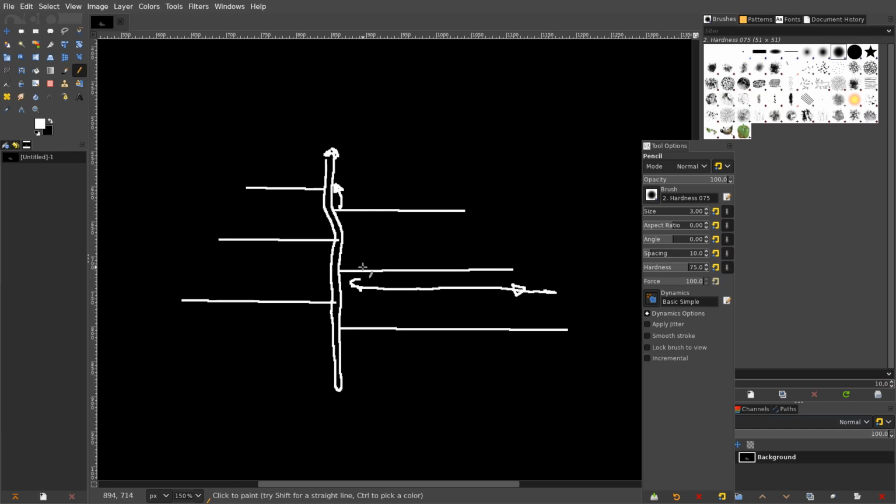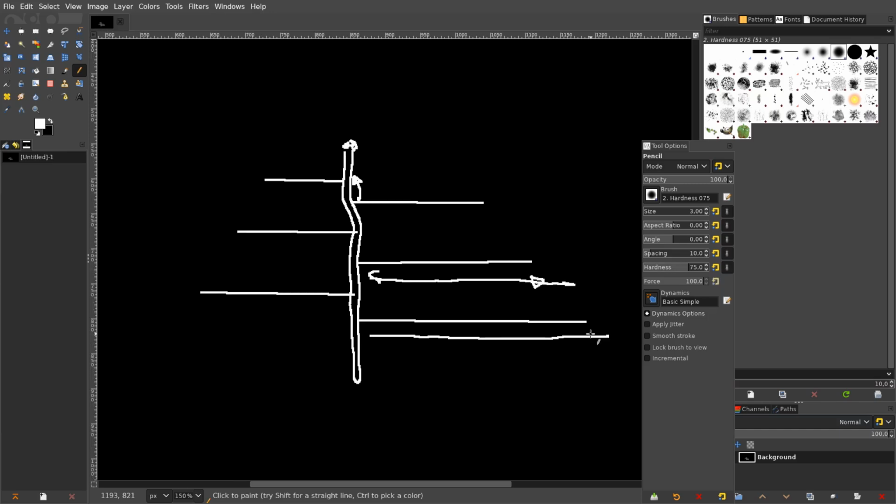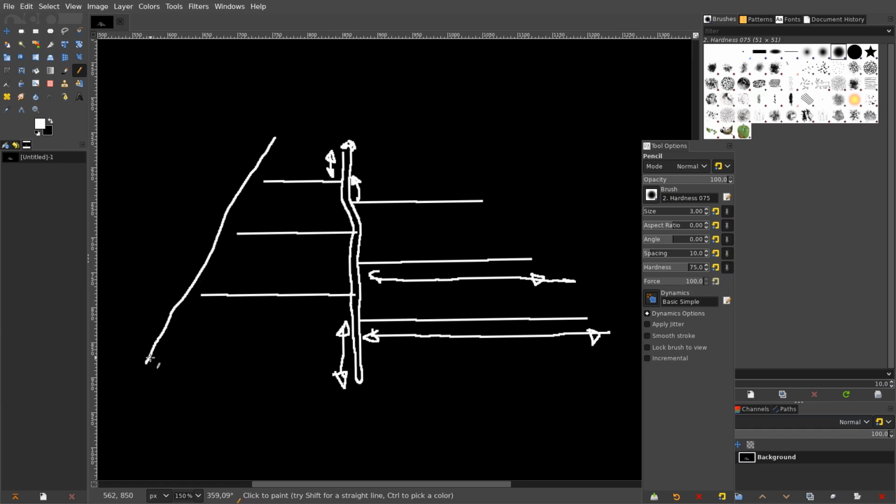So the interesting parameters of our antenna are going to be our base length here. The length here is also going to matter, as is this distance here, and we also need to be able to change the angle here of how pointy the antenna is, basically. You can also express it as a function of how long this element is, which might be easier in our meshing in Blender. We will see. And then you also might want to adjust how close together these are as a scaling factor on this axis, to see how this changes your antenna properties.